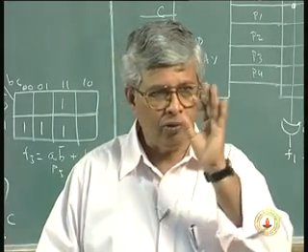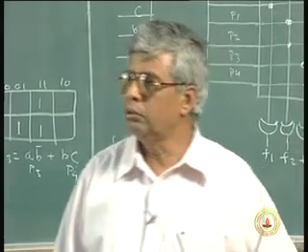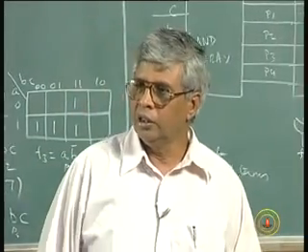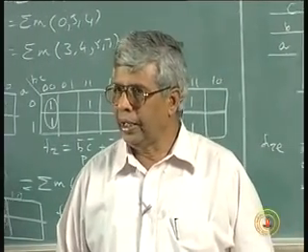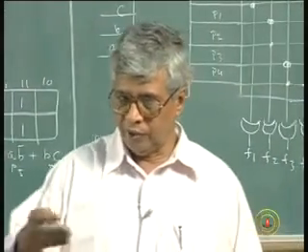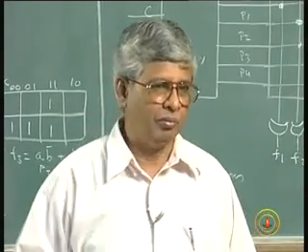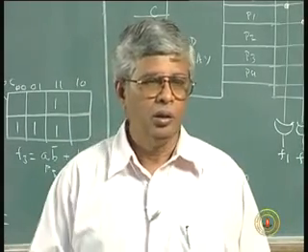Supposing I have 4 inputs and 7 outputs, in the case of a binary to 7 segment decoder, if I can share some of those terms across the outputs, to that extent I don't have to reproduce that gate again. Same concept here.